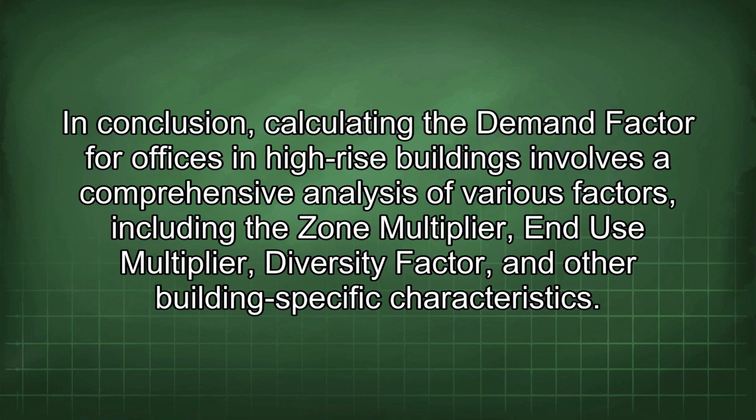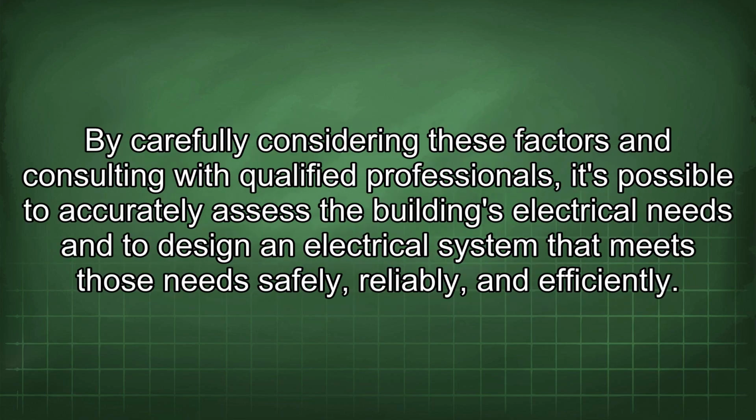In conclusion, calculating the demand factor for offices and high-rise buildings involves a comprehensive analysis of various factors, including the zone multiplier, end-use multiplier, diversity factor, and other building-specific characteristics. By carefully considering these factors and consulting with qualified professionals, it's possible to accurately assess the building's electrical needs and to design an electrical system that meets those needs safely, reliably, and efficiently.